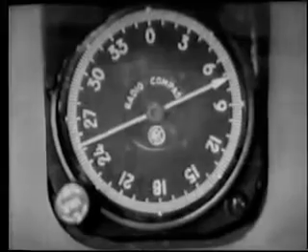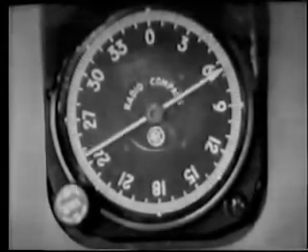We've moved away from our last position. What is the direction to the station now? He's turning right until the needle reads 0 to find the heading to the station. The instructor marks one up for him. That is the simplest and best method to use when you plan to go directly to the station. But there will be times when you want to know the direction to the station without having to change aircraft headings.